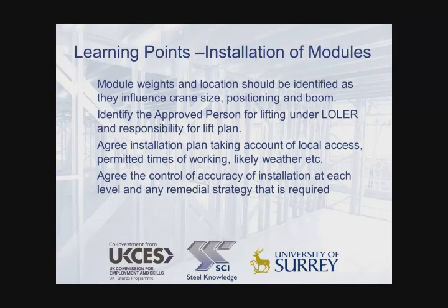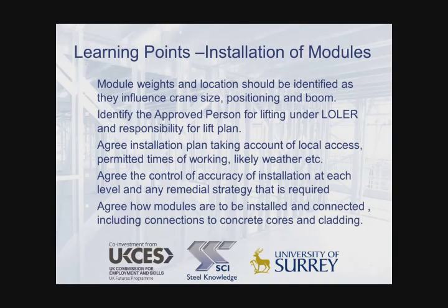It's also necessary to agree the control of accuracy of installation at each level and any remedial measures that are required. And also to agree how the modules are to be installed and connected, including connections to concrete cores and cladding.